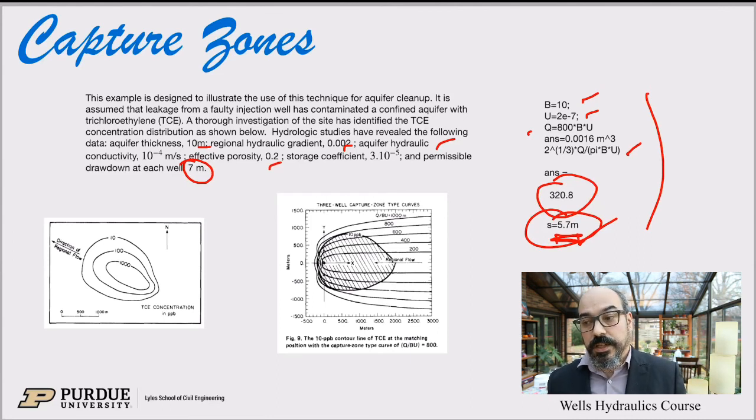So they're literally injecting the soil and maintaining the soil or water quality to favor, enhance, or facilitate the remediation in situ, inside the aquifer itself. So we typically isolate and then clean. I'll talk about this in the next video.